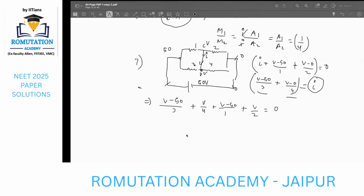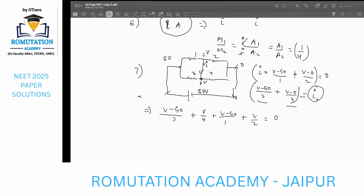So if I try to solve this equation, I have done nothing but substitute the value of I over this place, so that only one variable is left. Okay, so can I write this as V minus 50 into 1 by 3 plus 1, taking V minus 50 as common from these, and V by 4 plus V by 2, that can be written as 3V by 4. So that becomes the overall equation.